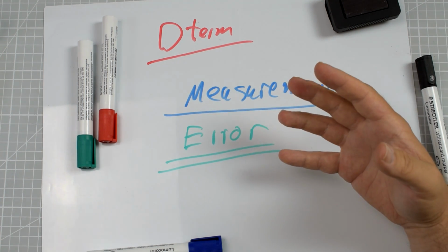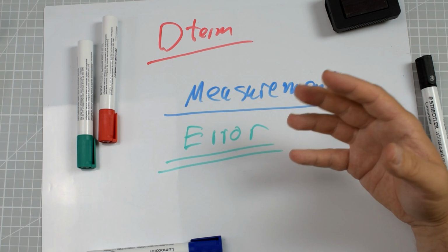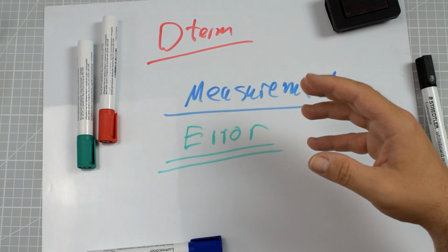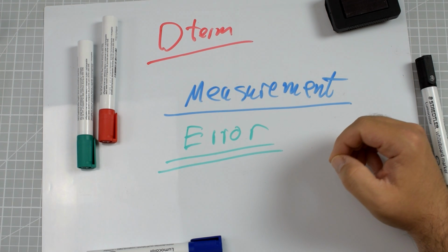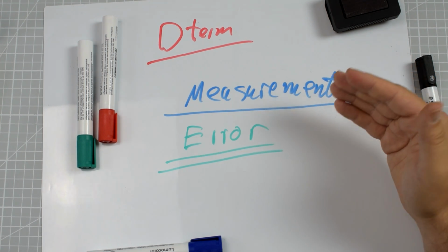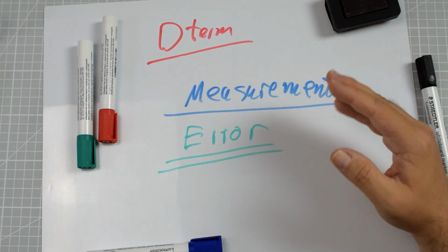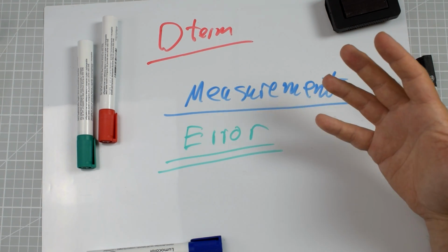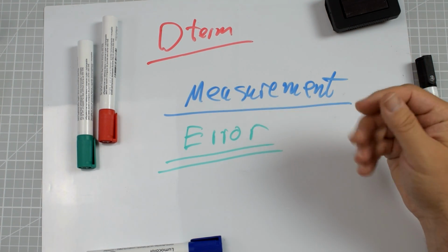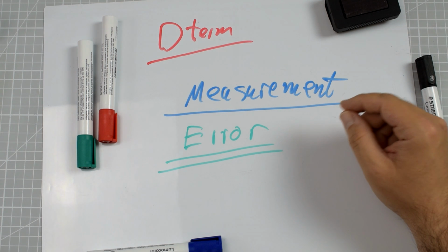You do not feel like you are flying through jello, because the movement of the sticks influences how much of the D term is computed and fed to the motor. So the quad, because we are talking mainly about quads, responds slightly more eagerly to your commands.